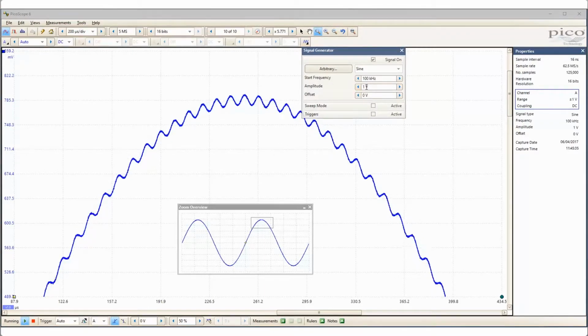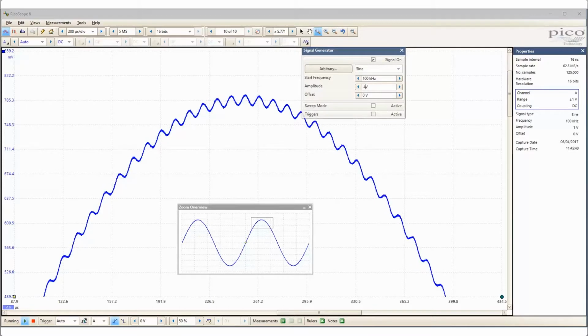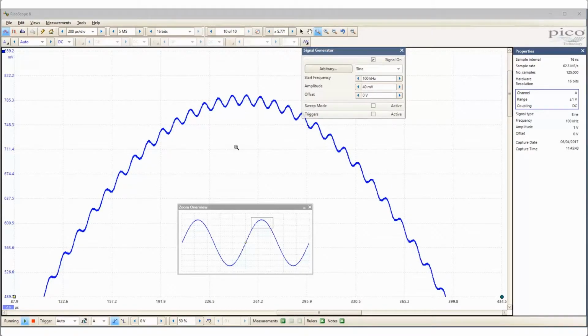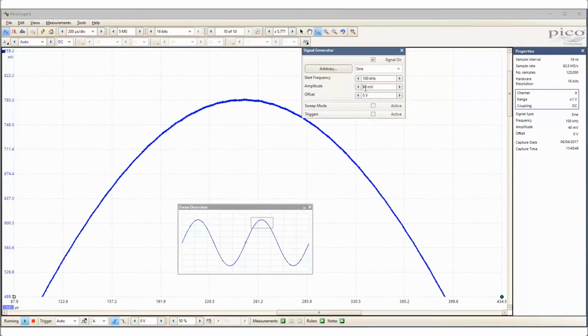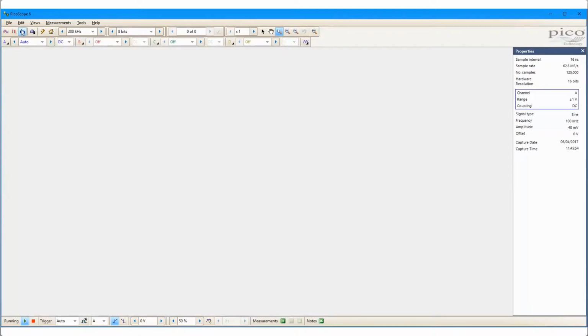Dynamic range is the ability to see low-level signals in the presence of high-level signals, and is often measured in dB. To show this, I'll reduce the interference signal until it's no longer visible in the time domain, even in 16-bit mode. And then I change the display from the time domain to the frequency domain by selecting spectrum mode on the oscilloscope.